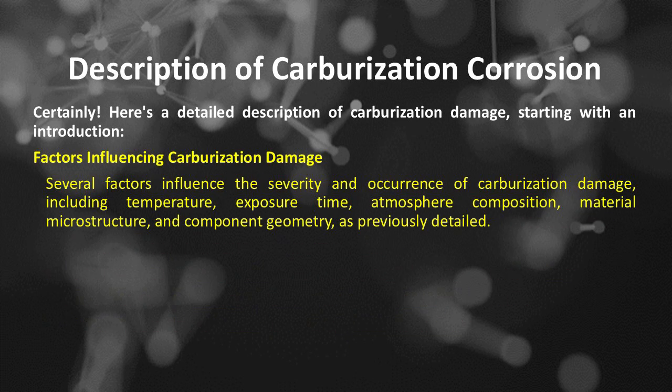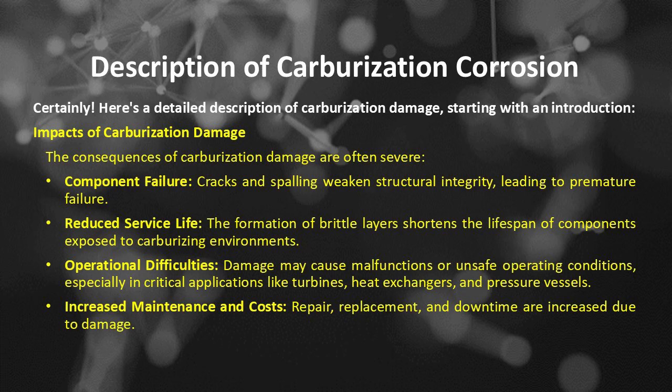Then, the factors influencing carburization damage. Several factors influence the severity and occurrence of carburization damage, including temperature, exposure time, atmosphere composition, material microstructure, and component geometry, as previously detailed. Impacts of carburization damage. The consequences of carburization damage are often severe. Number 1 is component failure. Cracks and spalling weaken structural integrity, leading to premature failure.